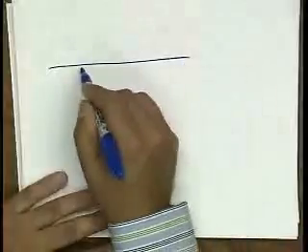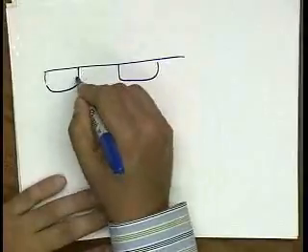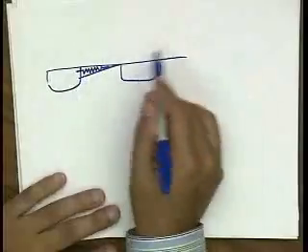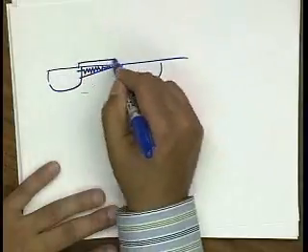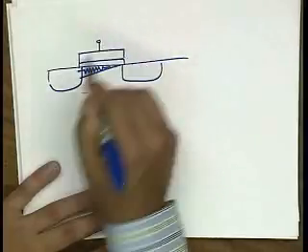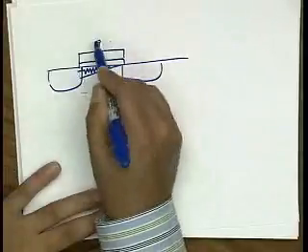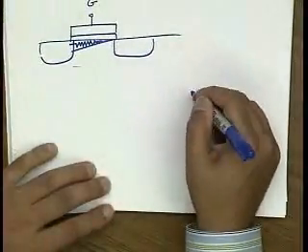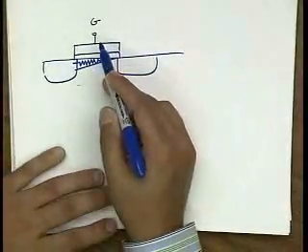Now, again, I won't go into too much detail, but there's one more wrinkle that we have to at least mention about FETs. So in a FET, the noise is all due to this, effectively, besides the parasitics. All the noise is really due to this channel, right? But it turns out that a lot of times what we're interested in is the effective noise seen at the gate. So I haven't talked about this yet. We'll talk about it next lecture. Sometimes it's very convenient to what we call input refer this noise. Okay?